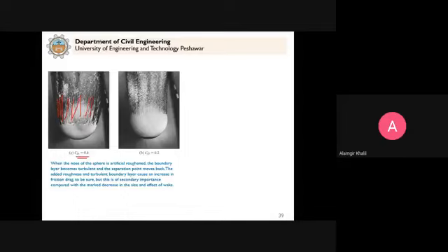Now what we can do in this experiment is that if the front of this ball is artificially roughened, from smooth to rough, this aided roughness and turbulent boundary layer cause an increase in friction drag, but you can see the shifting of the wake, it has shifted back.